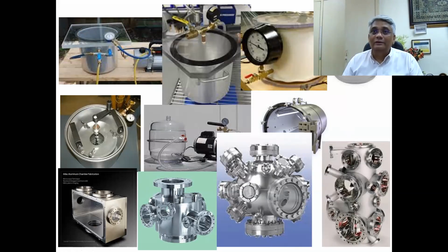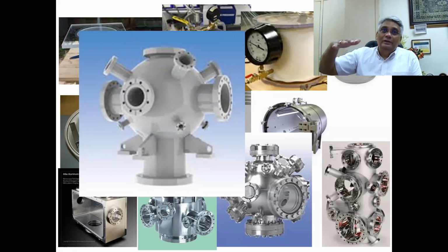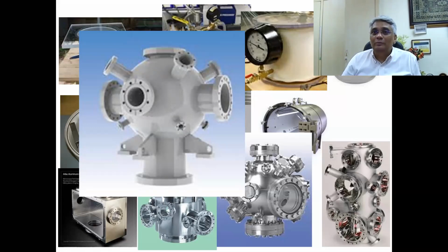You still get good vacuum inside these chambers. See that? And this is a pumping module, the chamber, inside which the deposition happens. And also today we have in situ monitoring. You can actually see how the film is growing when the growth is happening. This is the beauty about today's technology, leading to the process where I can actually monitor the crystallinity of the thin film that is growing on top of the surface.